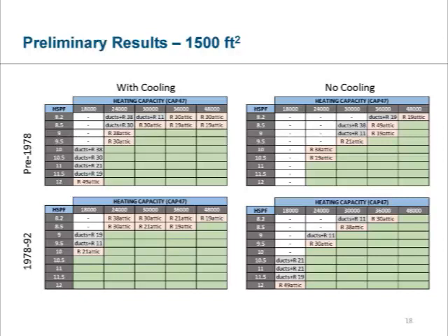And the other thing, Farhad, when you have these eras, can you please make sure that they are very clear that those are code? Because you don't want buildings that were built in 1978 to assume the same thing as buildings built under the code in 1978. This building wouldn't be coming on until after 1980. So this is pre-1978 code, and 78 to 92, delayed by 2 years or something. You should be clear that that's not the vintage of the building, it's the vintage of the code that it was built on. That's real world. Yeah, I appreciate that.